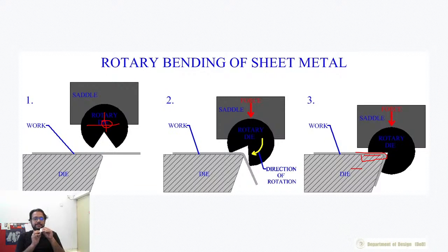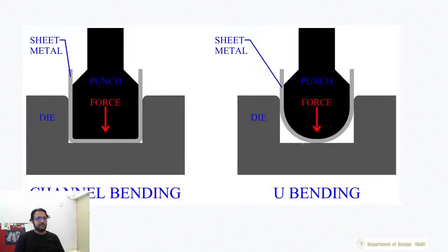Let's say if you want to bend 90 degrees, you need to bend the material a little more than 90 degrees, or a little less than 90 degrees, that means towards 0 degrees, so probably something like 85 degrees. But these exact values depend on the material that you are using. Let's say steel would have a much larger spring back effect than aluminium.